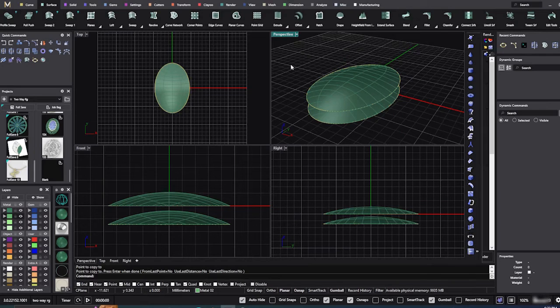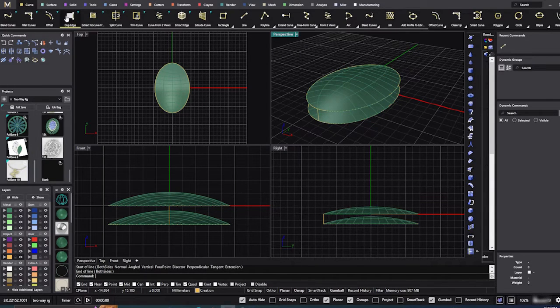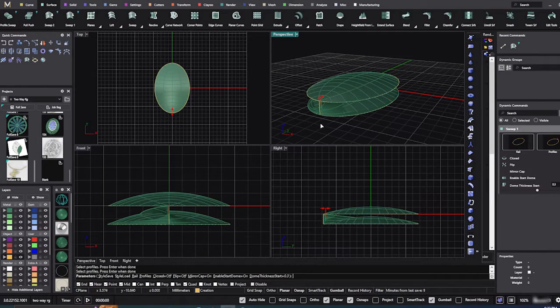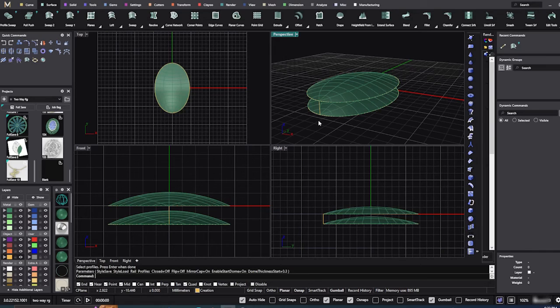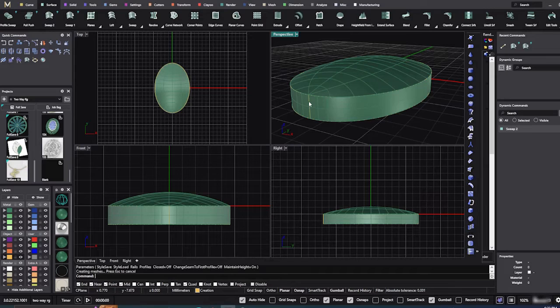It's totally up to you. And then I'll go back to my curves and get my line curve, go to my quad, first change to yellow, go to my quad snap, quad, and then we'll do another surface sweep, surface 1, with this curve, that curve, and that profile, and hit enter. Oh, I did surface 1. Don't want to do a surface 1. Make sure it's a surface 2 sweep. This curve, that curve, and this curve, and hit enter. Okay, there we go, and hit enter again.